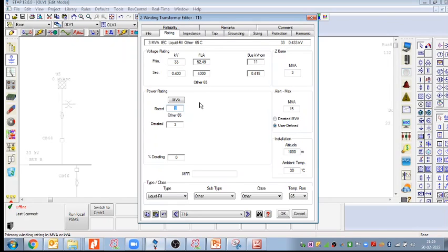If we go with 2.5 MVA, then it is 3300 ampere. Generally the maximum rating that we can take, if we go to 5 MVA, is 6667. I don't think a 6667 ampere rating breaker is available. I think the maximum breaker rating available is 6300 right now. You can see the catalog and the market availability, and based on that you can select. If 6667 is available, then we can go to 6667. Otherwise, we can go around 3 MVA or 4 MVA. With 4 MVA, yes, 5000 ampere is available.